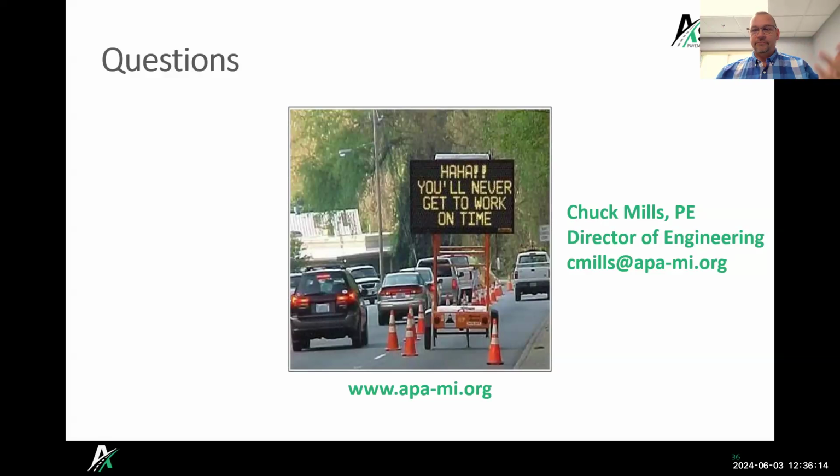There's another push recently to try it again. You really have to be able to characterize the material, and then how is that going to affect my mix design? So I know years ago they tried using these glass beads, and that had some issues where the mix wasn't very stable. So then I think they tried some more crushed material type things, and you can try that. And then it's a lot of trial and error. It's kind of going through that mix design process.